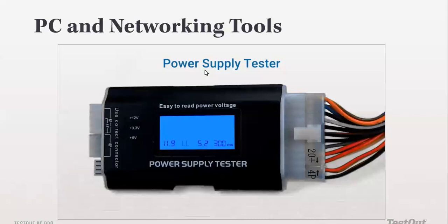You will know, oh, it's this cable that I plugged this one to. So that's how it's done. You plug the tone generator at one end of the wall, and then you use the probe to move it along the server rack. Here you'll be able to determine that, oh, it is this cable. When it blinks, you know that is it. So this is a cable tester, a digital variation of a cable tester.